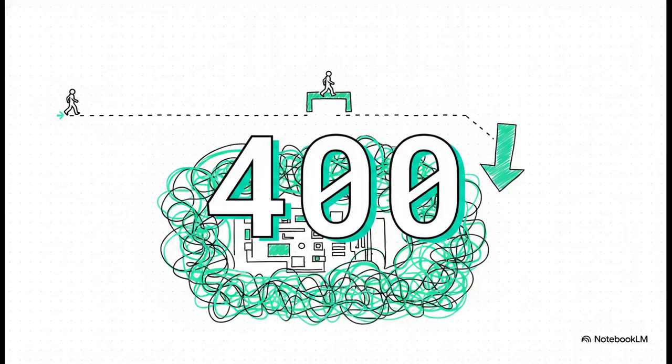And this brilliantly illustrates why we simply cannot just rely on standard process flowcharts. Think about it. Two process maps can look completely identical on paper, outlining the exact same logical steps, but only a physical mapping reveals that one layout requires 40 feet of walking per cycle, while the other takes a staggering 400 feet. 400! That is a massive, massive difference in efficiency and worker fatigue that a standard flowchart simply is not going to show you.